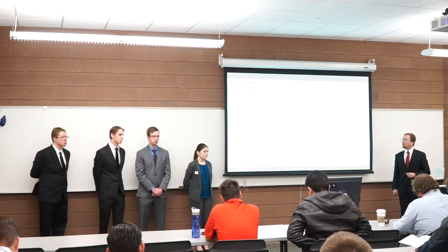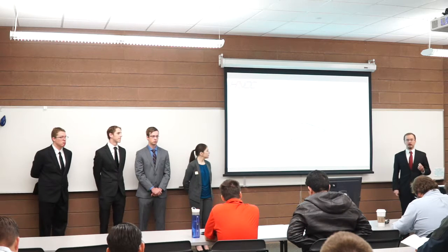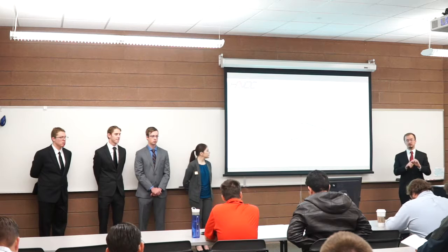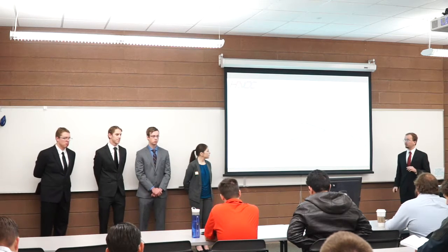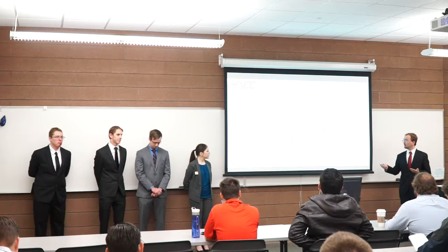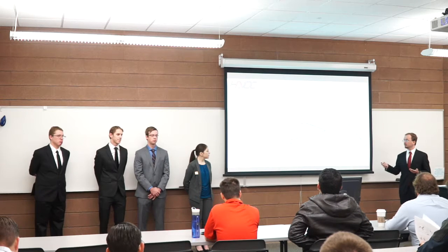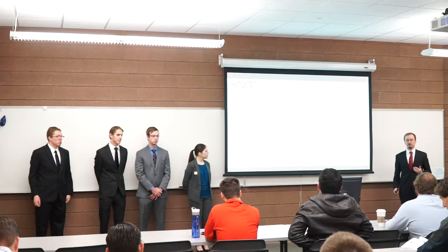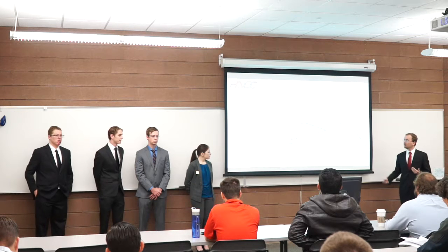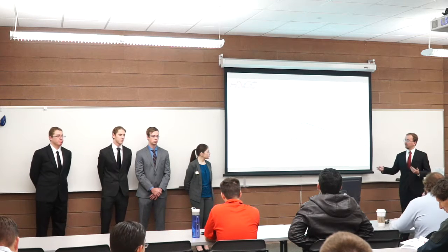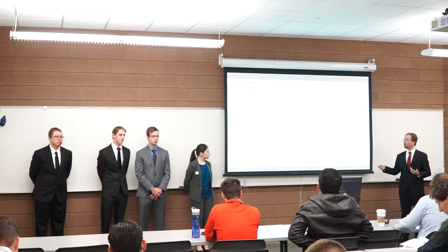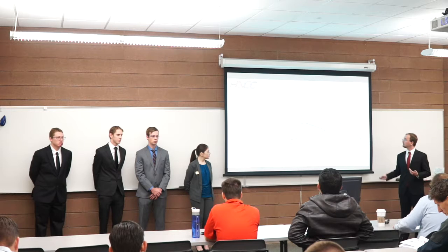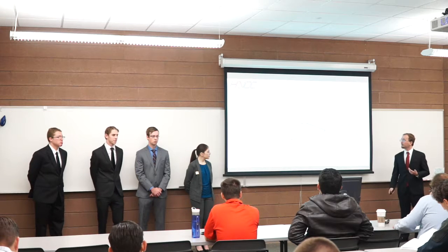For the fingers, due to the fact that we have the angle between the distal and middle phalanx being fixed, we can simplify the problem of what would normally be a 3-degree of freedom problem down to a 2-degree of freedom problem. And this reduces the amount of calculations we would need to make for those thetas. Right here are the equations I am using to calculate theta 1 and theta 2, as well as theta 4.